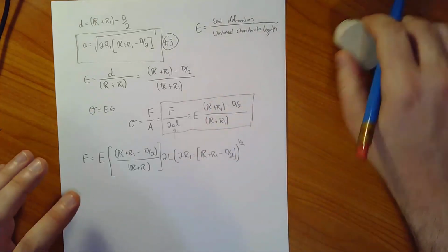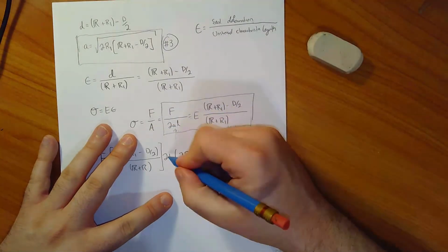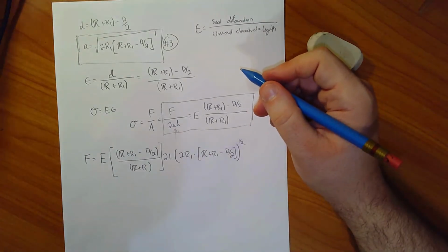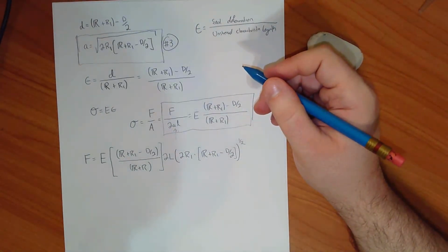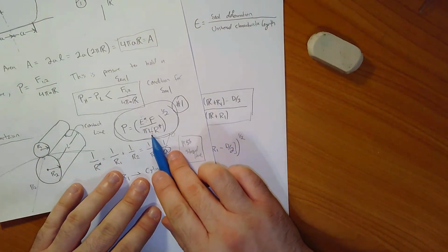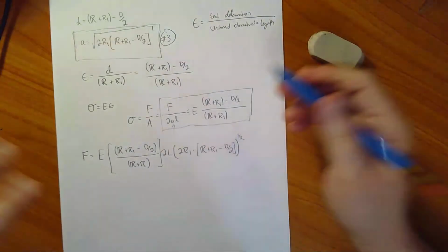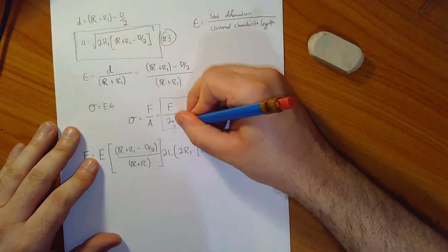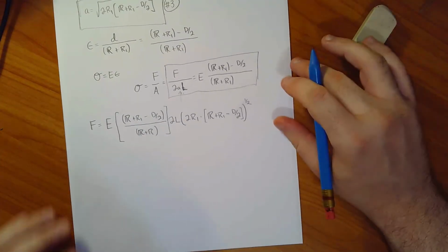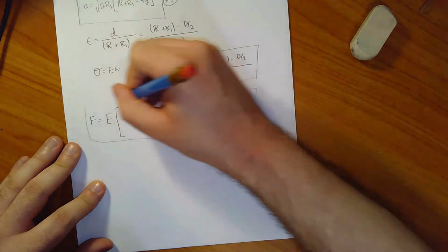Okay, and I should also be really clear about this, that this L and this L are the same L. So I'm going to use capital L, and that's because I use it here in my Poisson, in my Hertz equation. So I'm just going to call this capital L. It's again the circumference of the O-ring. Okay, almost there. Now I'm going to put this guy in a box. I'm going to call him number 4.